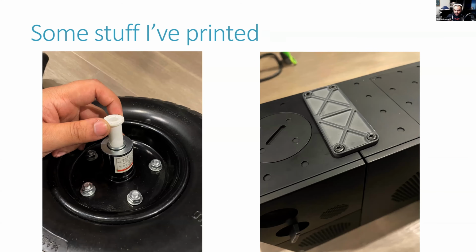That's a great question. In terms of measurement, the calipers are accurate to plus or minus 1/1000th of an inch. To put that in perspective, a sheet of copy paper is 4/1000th of an inch. The calipers are accurate to 1. So that's part of the issue. And what material do you use for the bushing? Rigid 10K printed on the Form 3. I have a feeling it'll do pretty good, but I'll probably update my social media on how that works.